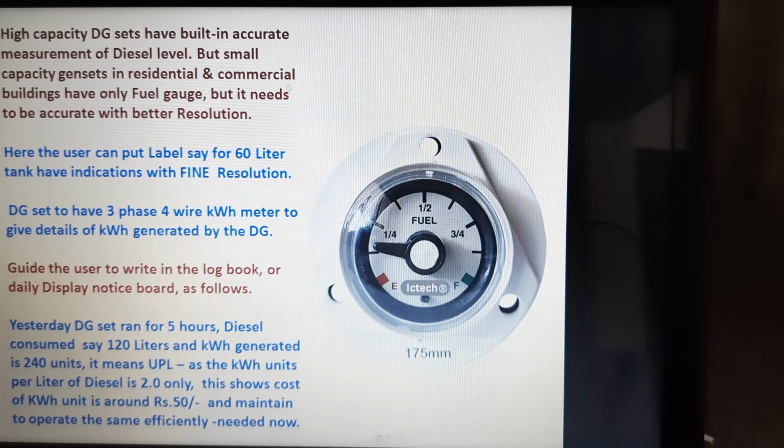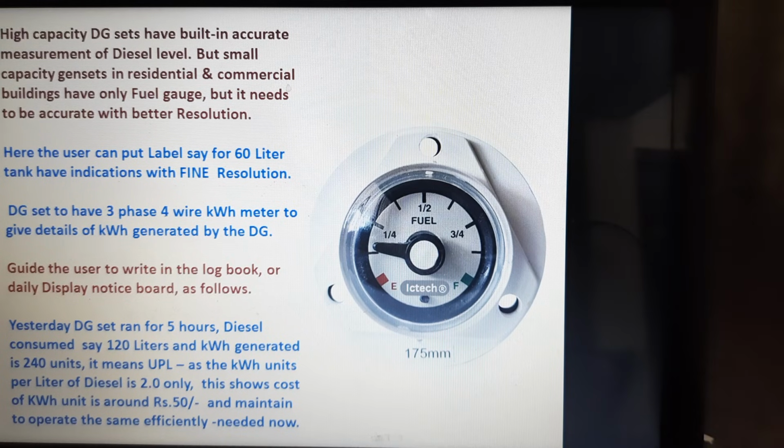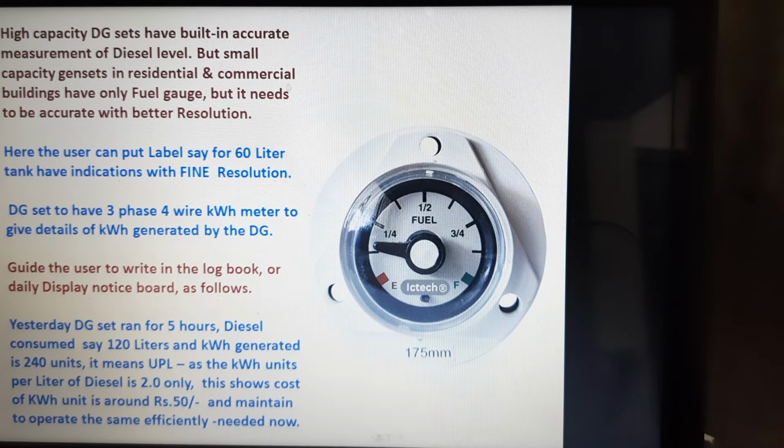Say if it is a 60 liter tank, you can put a label on every 10% step showing how many liters it is, so that daily, wherever there is a power cut and they are using the DG set, the user can see how many liters have been consumed that day. You also need a 3-phase 4-wire kWh meter to be installed in the genset. If it is not installed and it is working, it is fine, but if it is not there, it needs to be added on, so that you know the units per liter generated by your DG set, especially in buildings.